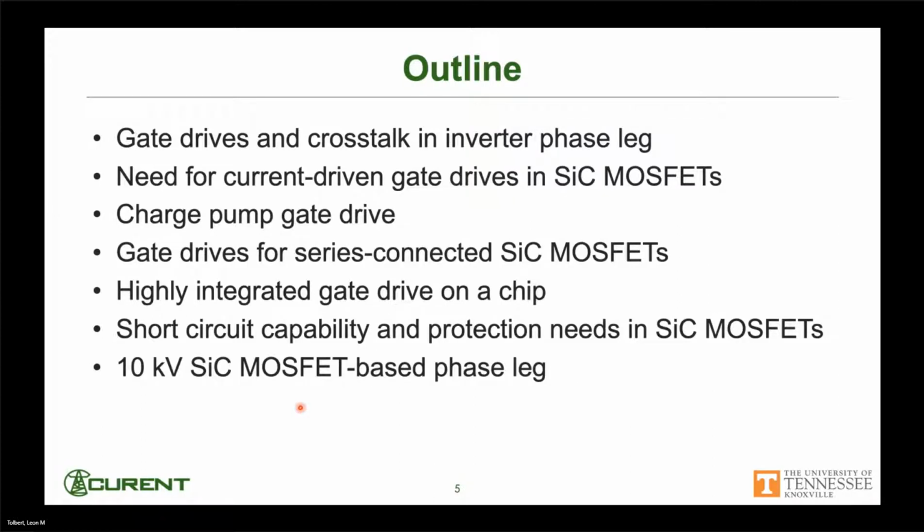Just briefly touch on a highly integrated gate drive on a chip that we've done. Cover some about short circuit capability and protection, and then touch on some of the work that we've done now with 10 kilovolt silicon carbide MOSFETs and the challenges associated with those.